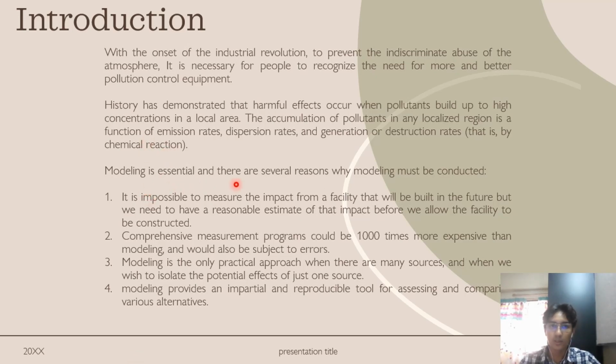Modeling is essential, and there are several reasons why modeling must be conducted. The first is that it is impossible to measure the impact from a facility that will be built in the future, but we need to have a reasonable estimate of that impact before we allow the facility to be constructed. Next, comprehensive measurement programs could be 1,000 times more expensive than modeling and would also be subject to errors. Then, modeling is the only practical approach when there are many sources and when we wish to isolate the potential effects of just one source. Lastly, modeling provides an impartial and reproducible tool for assessing and comparing the various alternatives.